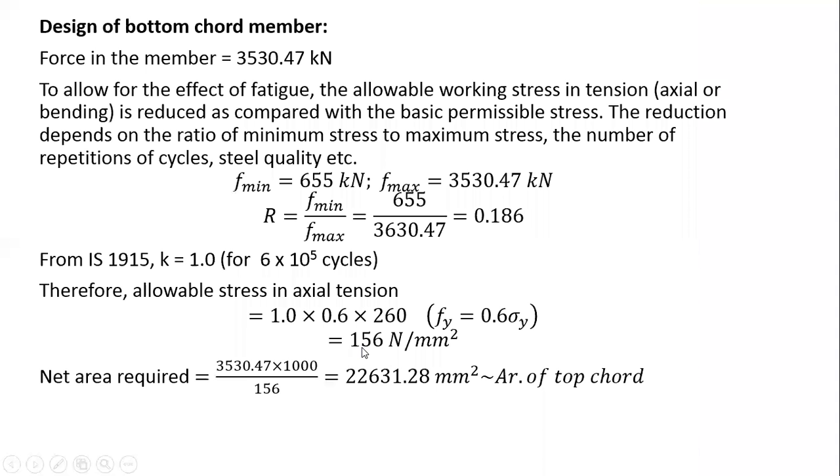Now I will come to the design of the bottom chord. The force in the member is already calculated. Now, to allow for the effect of fatigue, the allowable working stress in tension, axial or bending, is reduced as compared with the basic stresses. So my target is to reduce the permissible stresses in tension to account for the effect of fatigue.